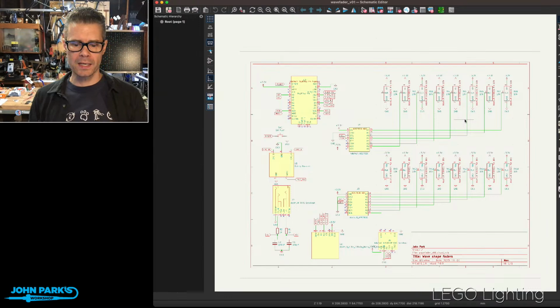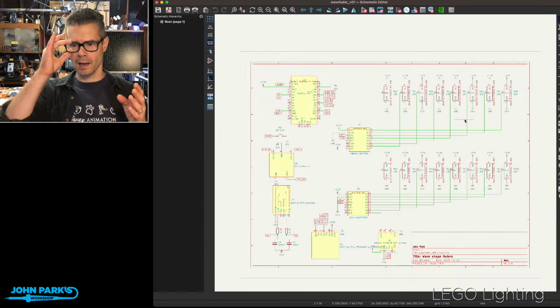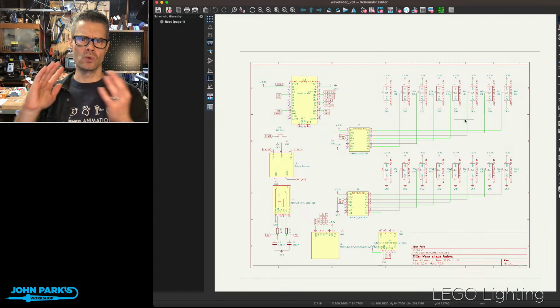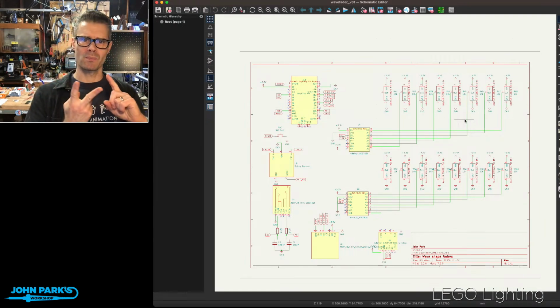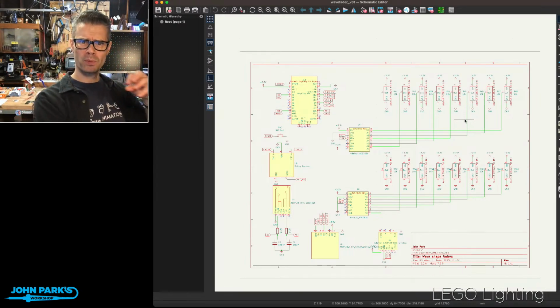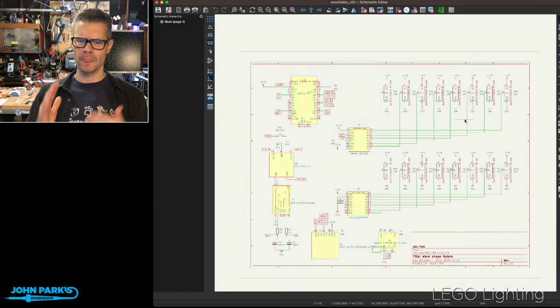I had initially put together a schematic and a breadboard diagram using Fritzing. I've sometimes made circuit boards with Fritzing, but it's a bit simple and a bit limited, and my main frustration comes in making new parts with different footprints. Can be a bit challenging, or even adjusting the footprints on existing parts. Usually involves a trip to Adobe Illustrator and maybe Inkscape, saving SVG files, bringing them in, finding magical places to save the files. So it's a bit of work.